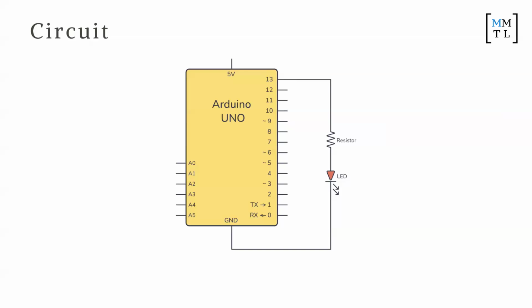So no analog. This one should be connected to the 5 volt. If you simply connect the 5 volts, it stays on all the time. We want the ability to turn it on, so you need to put a wire from pin 13 and then connect back to zero. Pin 13 is not connected; we need to connect the 13 too, and then back to ground.